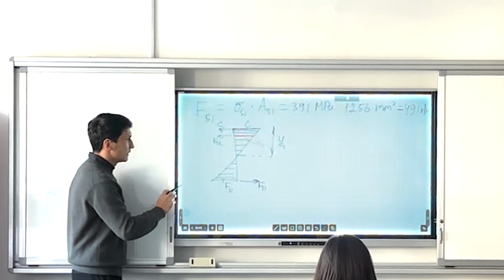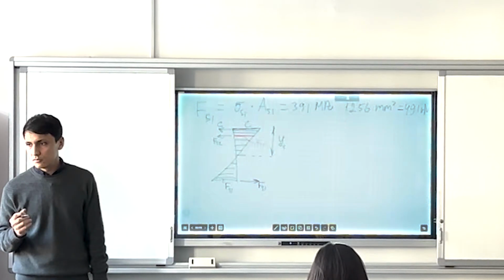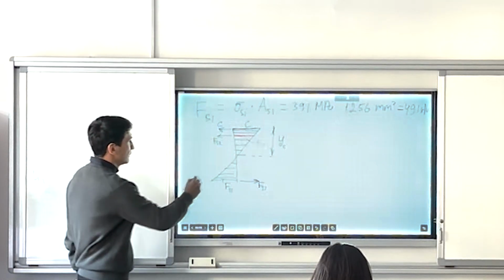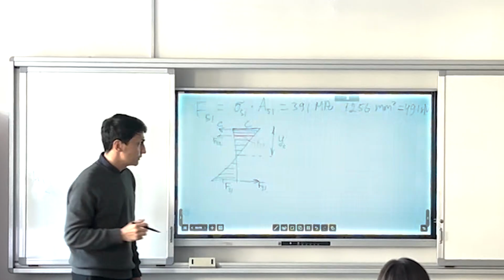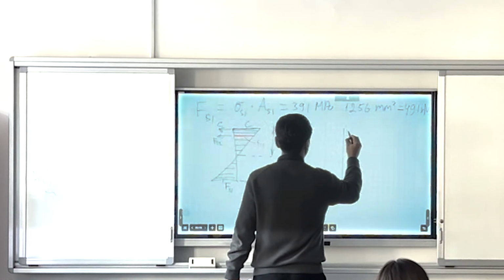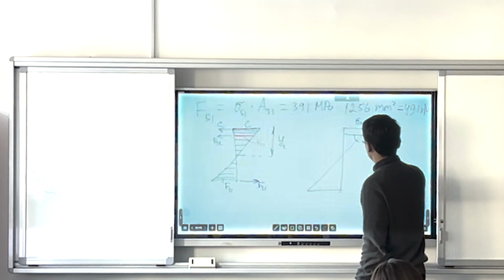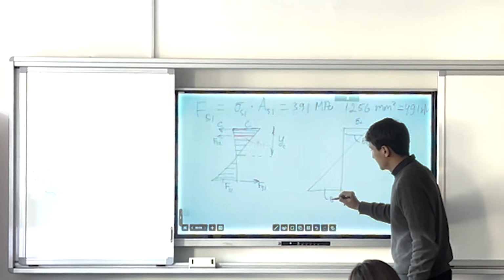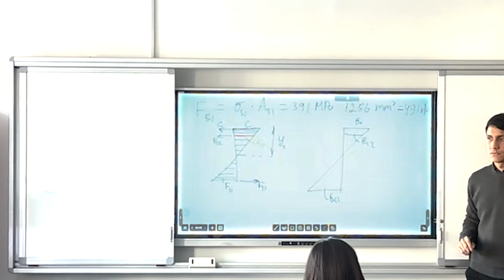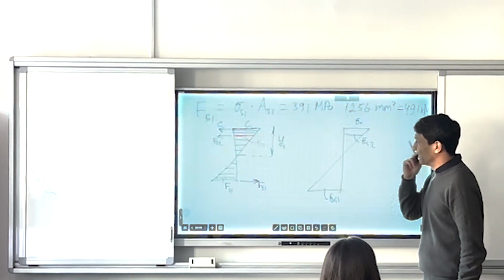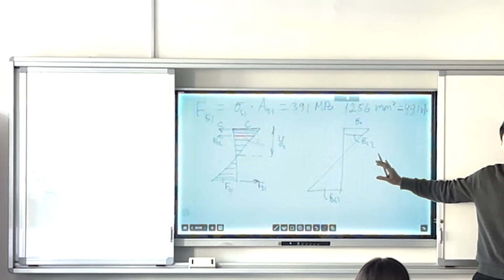Well, this is the stress-strain relationship, because we have linear law, I mean we are in an elastic region. This line will be linear, okay? Stress will change linearly. So basically it is derived from this one. This is sigma concrete. Here we have sigma S2. Here we have sigma S1. Is it clear? Well, this is the diagram of the pressure, diagram of the sigma stress.